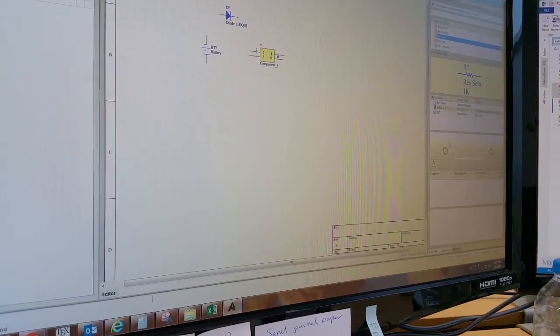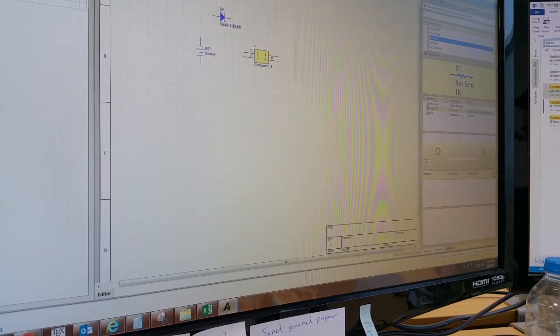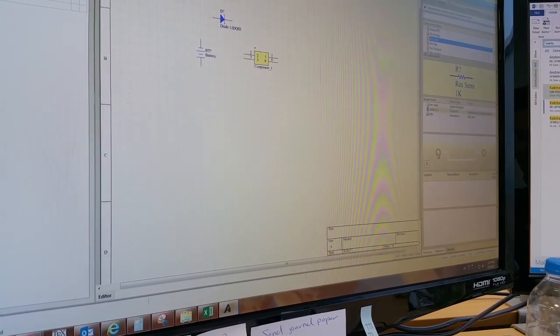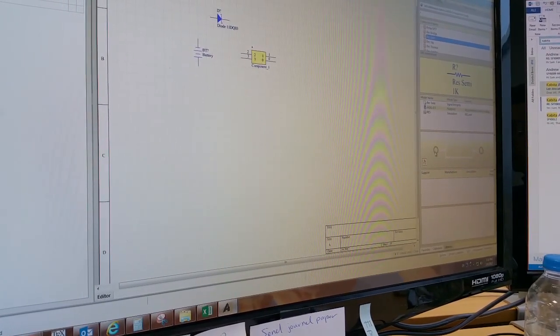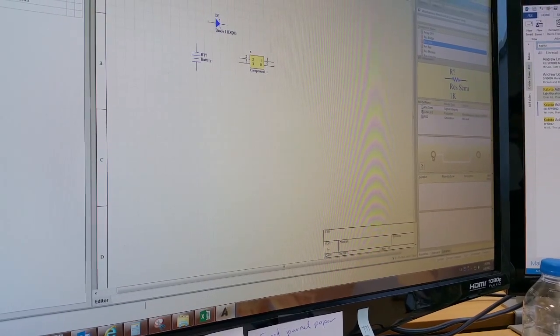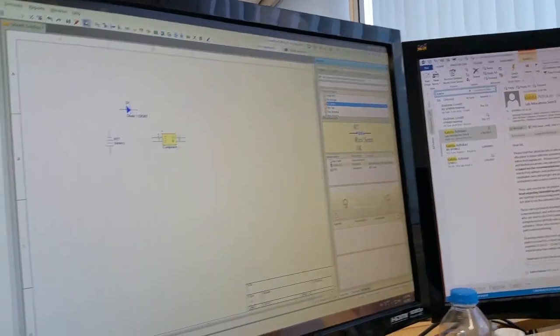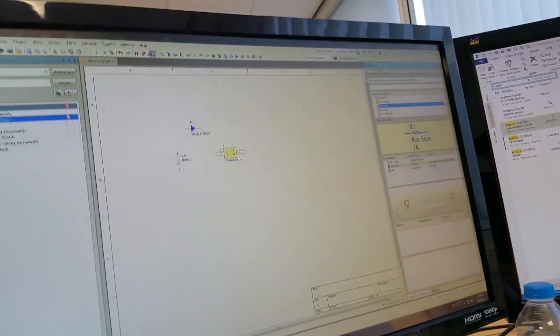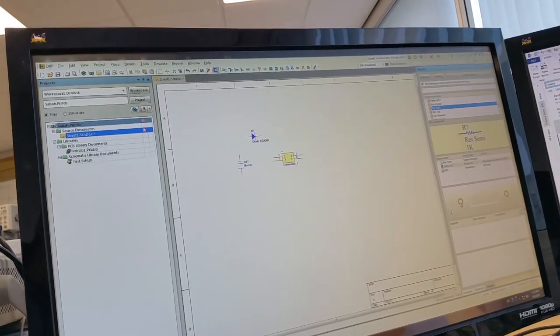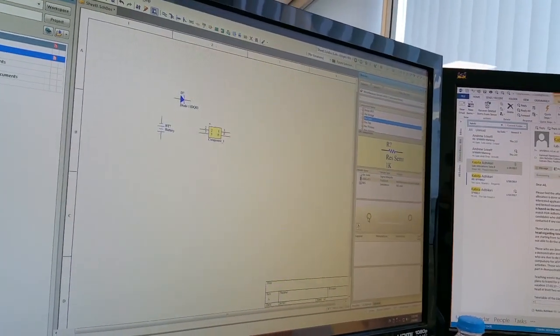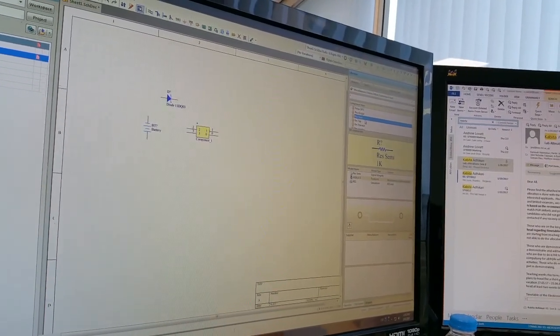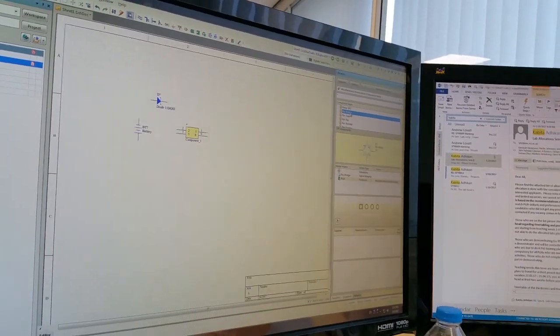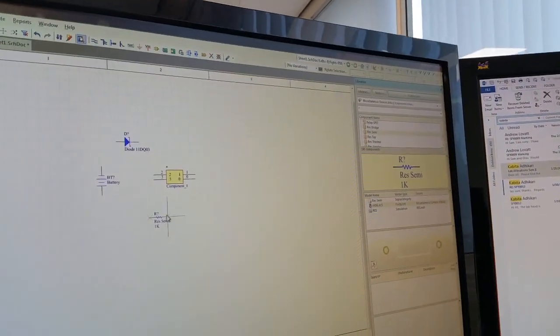You can change it because this resistor now is a leg resistance. You need to drill the PCB for the big component, this one. But if you want this kind of resistor, which is called surface mount, you need to change the layout, change the footprint. You can't change it? Yes, they have. You see, if I put that one now,